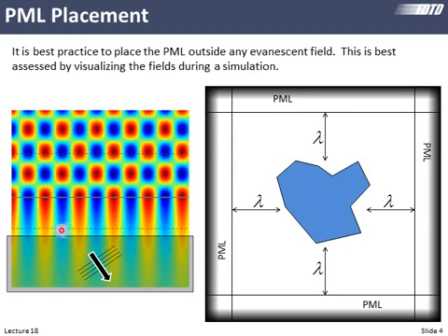So in our diffraction efficiency calculations, we ignore the evanescent fields because we assume they are not transporting power. However, if those evanescent fields touch our PML region where the refractive index suddenly becomes very high, these evanescent fields can now couple into propagating waves, we can have power essentially tunnel past our record plane here, and we won't record it as transmitted or reflected energy. That's bad. So we need to place the PML away from these evanescent fields so they don't touch.